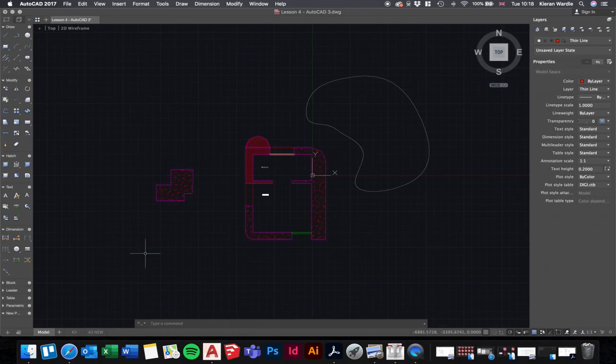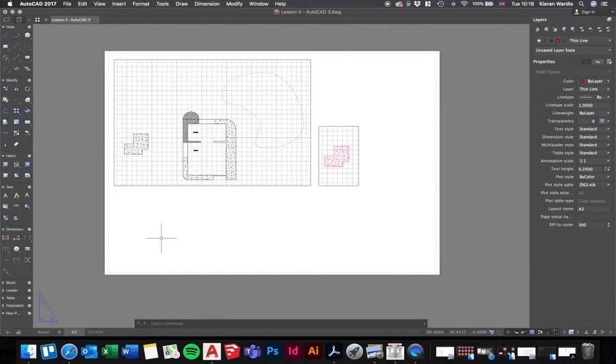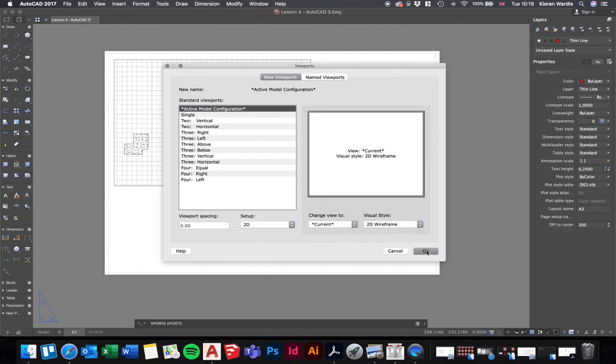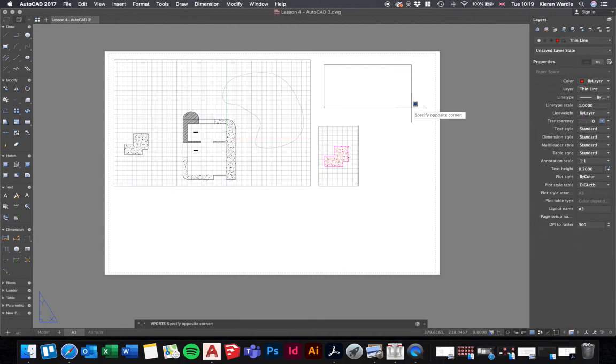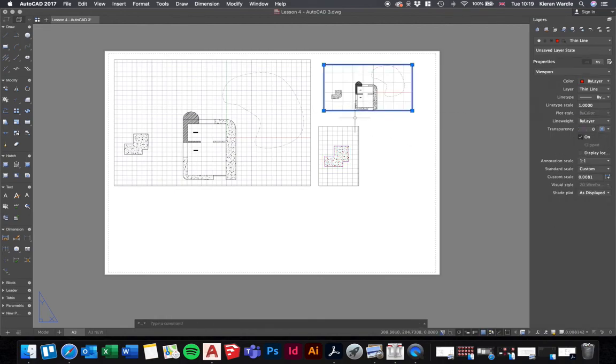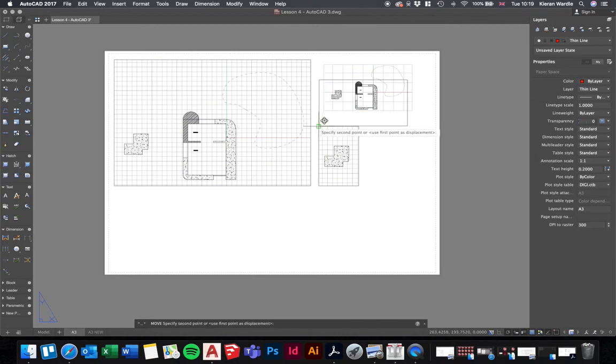And we've looked at how to create a layout here, and how to create viewports, and how to draw new viewports, and also how to adapt those viewports so that they create a layout that works for your piece of paper, and then also how to print it as a PDF. So we're getting to a point now where you may be able to draw your case studies.